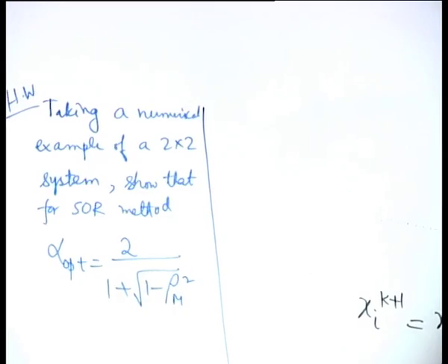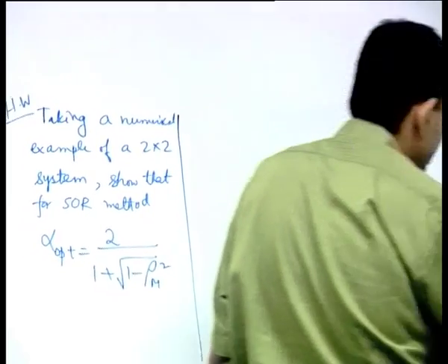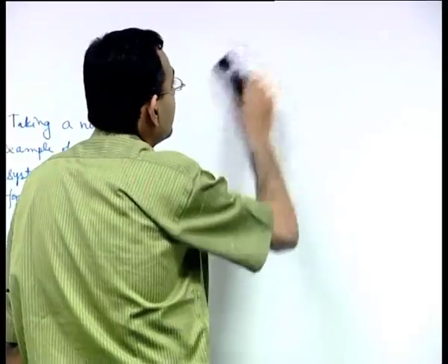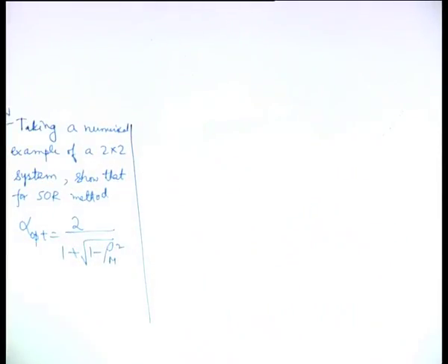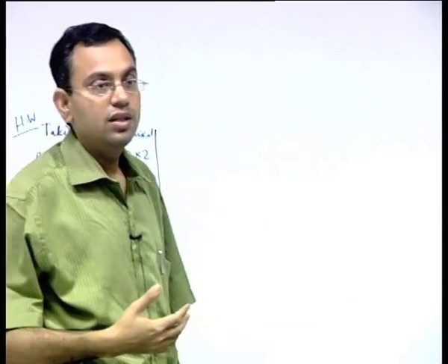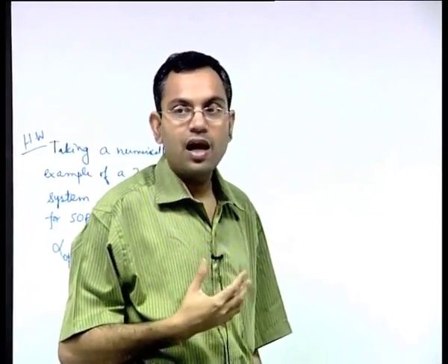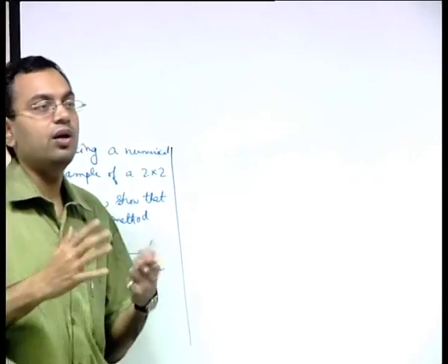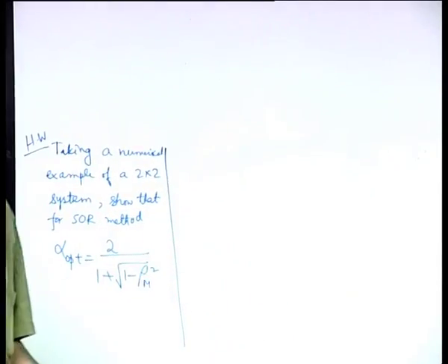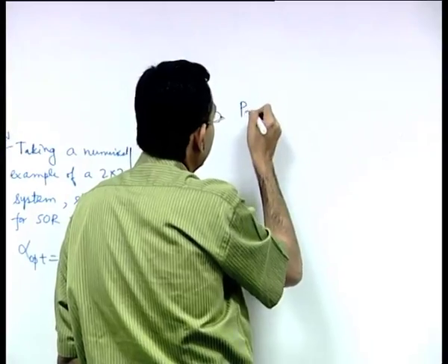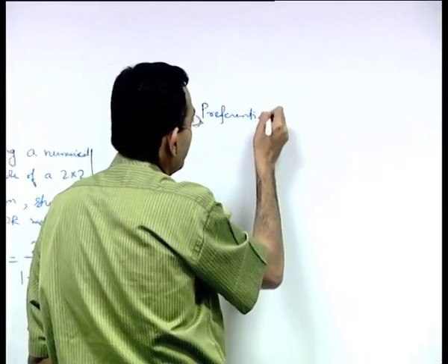Now we have learned some iteration methods and some elimination methods by now. The question is what do we prefer in CFD applications out of these two, if you have a choice. Very commonly we use the iteration methods as a preference. We will see later on that it is not always true, sometimes a combination of these is what we look for, but in general iterations are preferred. And why? First of all, some preferential characteristics of the iterative methods.